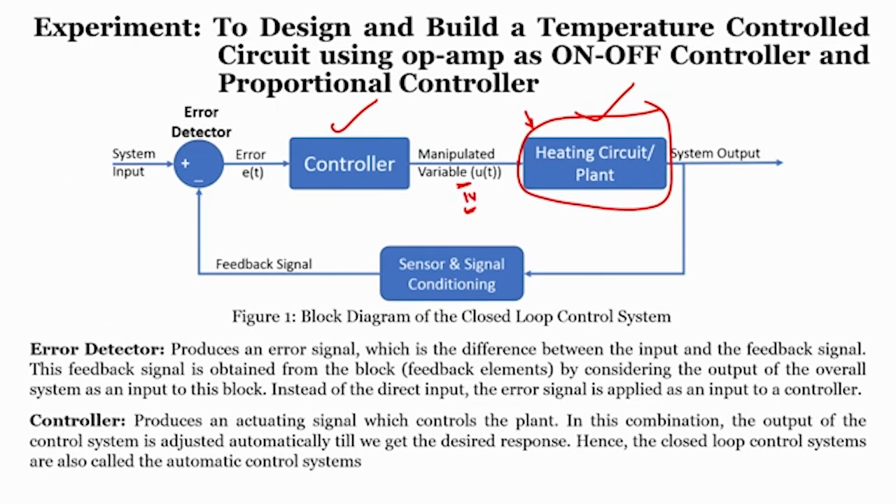If you change the plant, if you know what range it can operate in and what maximum current it can withstand, then based upon that you can tune these parameters and vary the output voltage. How can we do it? By changing the parameters of a controller. In order to understand that, we will look into the controller too. Now we will see the same working in Multisim.